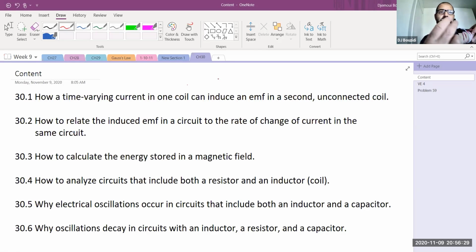Wrapped around. So now I have the ends for the wire that is white on this side, and the ends for the wire that is red on this end. So what I have in this case created, in a sense, is 2 different wrappings. Now, if I run a current through the white one, for example, and if this current is alternating, it's changing with time, that current will start from one end, go around, come after 11 turns, and come back from the other end, and now it's changing with time.